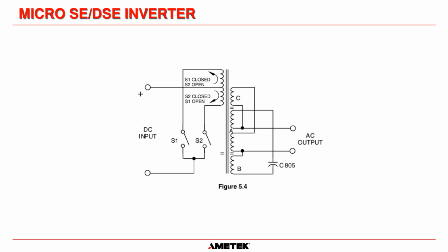This portion here is what we call our CVT, our constant voltage transformer. What a constant voltage transformer does is, for varying inputs on the primary, so the primary can go up or down, the secondary at this AC output here is kept constant.